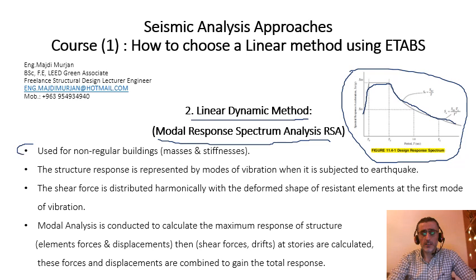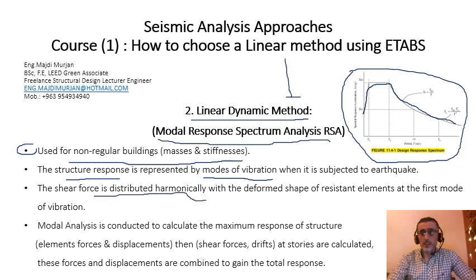This method is used for non-regular buildings in masses and stiffnesses, and it is more general than the lateral force procedure, and the structural response will be presented by modes of vibration. As we saw earlier, this shear force will also be distributed as a triangle,